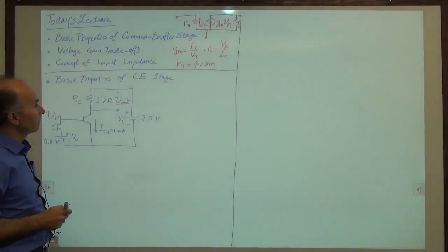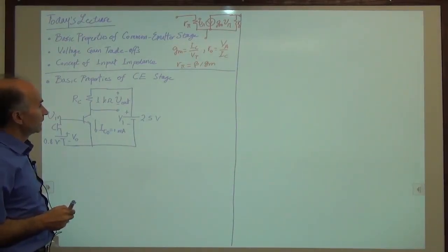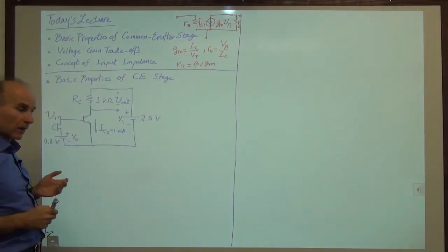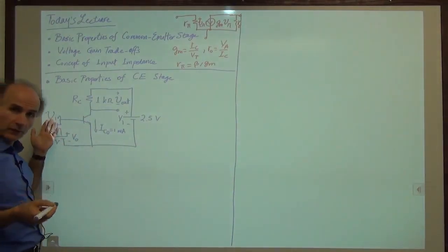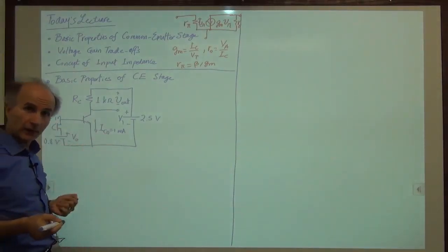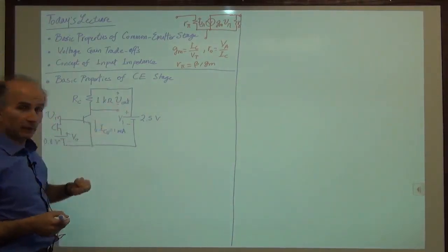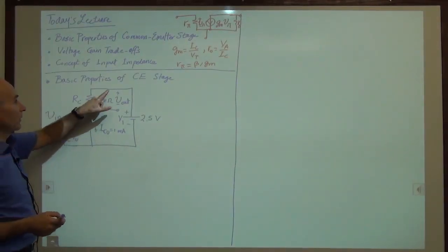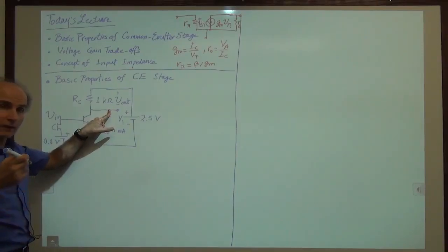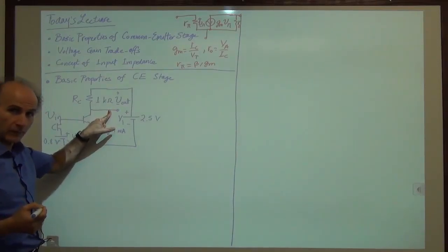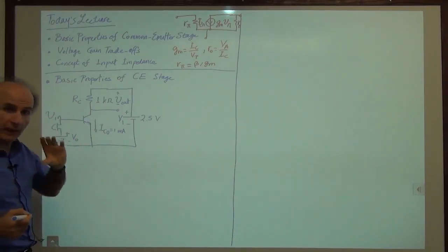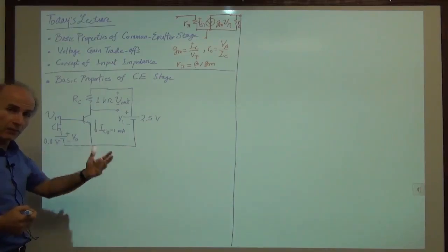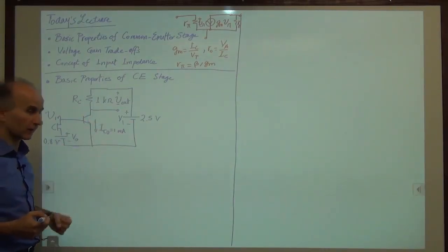Okay, so let's go ahead and plot these as a function of time. Let's say the input is a sinusoid of some sort, maybe a millivolt or so in amplitude. And then we'd like to plot V out. And in doing so, we want to plot everything that we observe here, not just the changes in the output voltage. So for that, I would use an uppercase notation for V in and V out, because uppercase means everything, the bias and the signal change, etc.